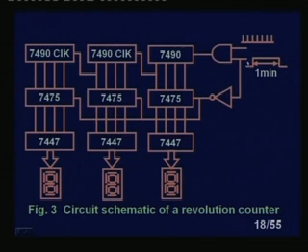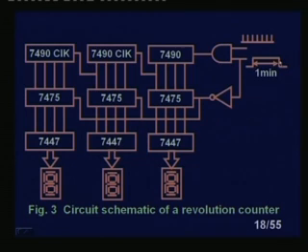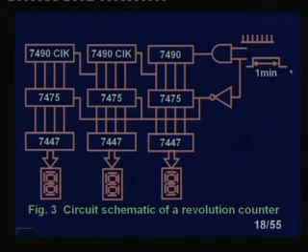This is a very interesting scheme that will be activated for 1 minute, and will count. So, whatever reading we are getting here will be directly in revolutions per minute, is it not? Because we have made the width of 1 minute. Mark to space: mark will be for 1 minute, space might be for 1 second, it does not matter. So, during that 1 second what will happen? Until this 1 minute comes, at the end of the 1 minute, whatever data is there will be displayed automatically, and it will remain in the same hold position. Clear?